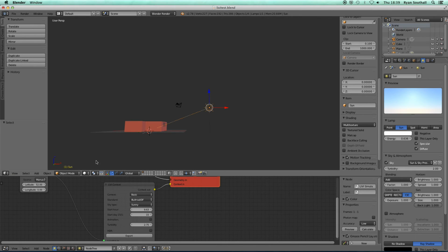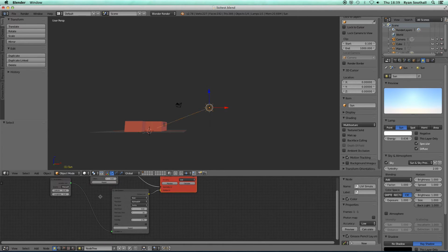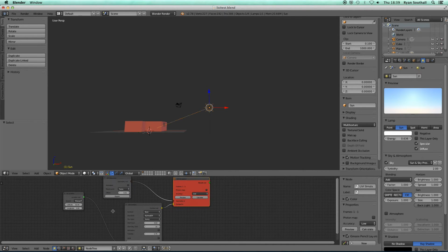We can see which frame we're currently on by this number here, 1. And I can change frame by my right and left arrow. We're on frame 1. This was the frame we were on when we did our export of our nodes. And because I haven't set an animation here or here, the animation range for the simulation is 1 to 1, which basically means we're only going to simulate frame 1.